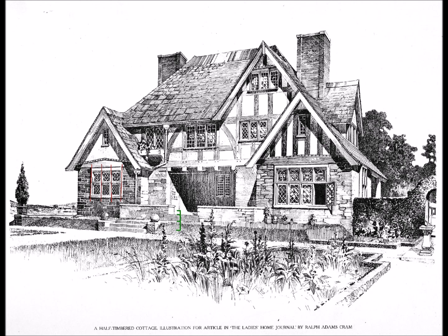Continuing to the right, we've got another section of wall, which appears at first glance the same as this one, which I said was 4 feet. But looking more closely, we're not seeing part of it because the corner of this gable is obscuring it. So I'm going to assume that's 6 feet wide. And then finally this 14-foot wide gable. So adding it all up, starting from the left, we have 12 plus 4 plus 12 plus 6 plus 14. That makes the width of the house 48 feet.